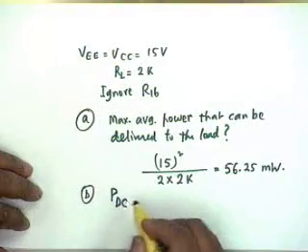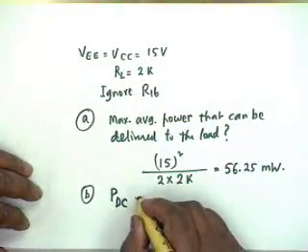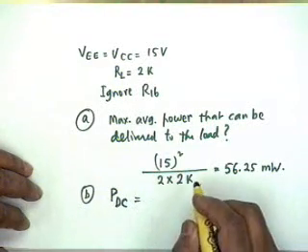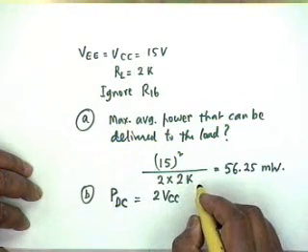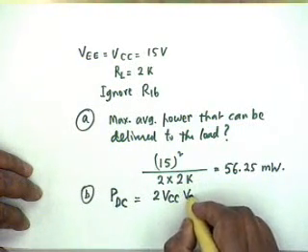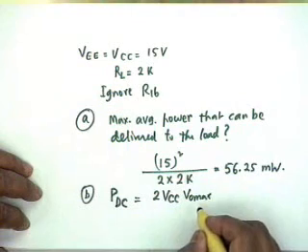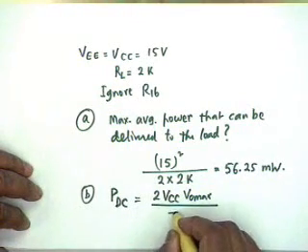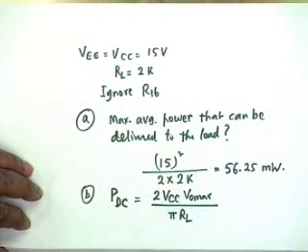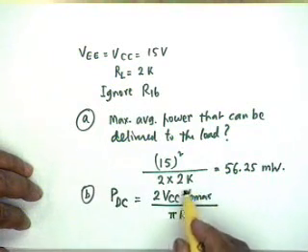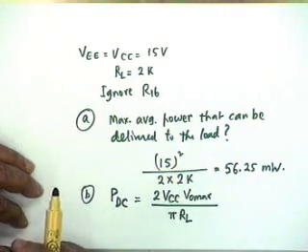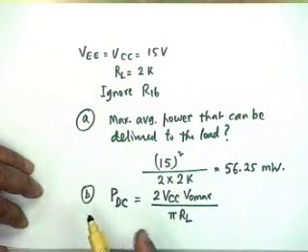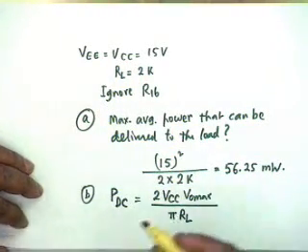If you recall, we found this as twice VCC multiplied by VO max divided by pi RL. VO max by pi RL was the average DC current, and we multiply by twice VCC, that is VCC minus VEE.